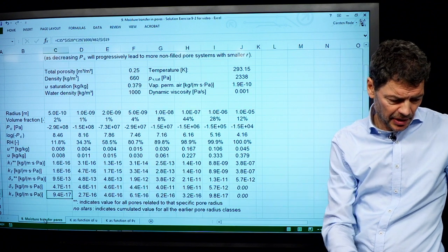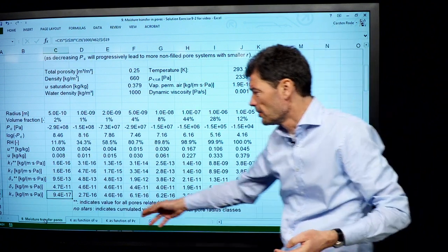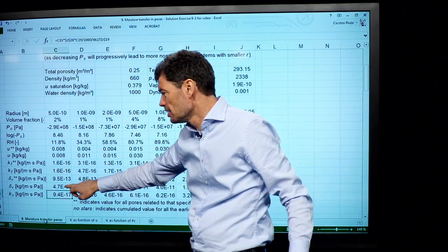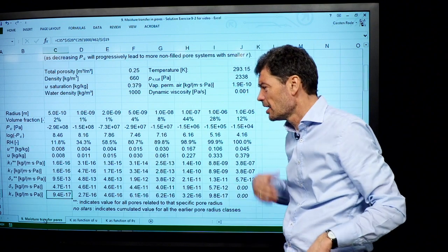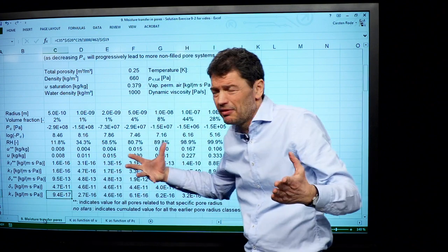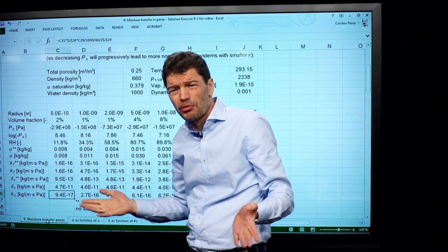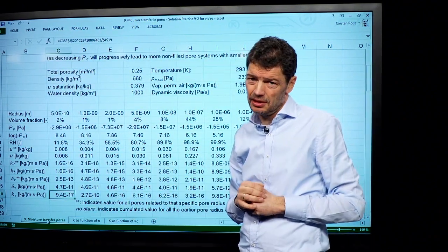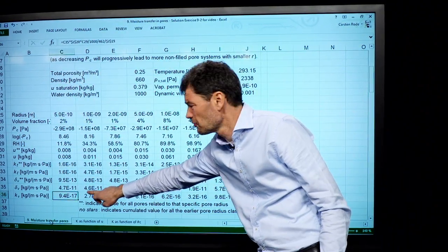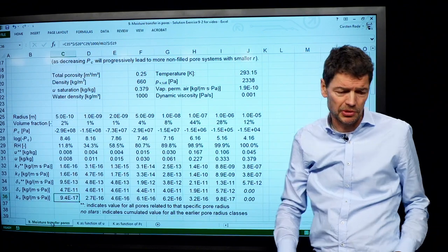Now, in the bottom down here, for the vapor, we have the calculation from the normal water vapor permeability, using the formula we had on the last slide, of how it translates from water vapor permeability into a value kV. That is the same number, but referring not to water vapor pressure but to the capillary pressure as our way to represent water vapor content in the material. So that is kV, one of the values that we should plot, and before we calculated KL down here in this row that we should plot.